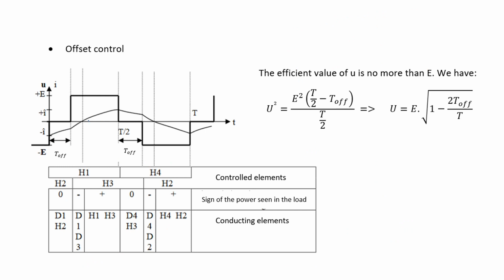And this is a different way of controlling the switch. You use a different type of switch function, for example like this, to have some off period. So the waveform is like this. Actually, with this waveform, when you use a filter, it looks more like a sine wave, better like a sine wave, right? When we use a filter, that's why this is useful.